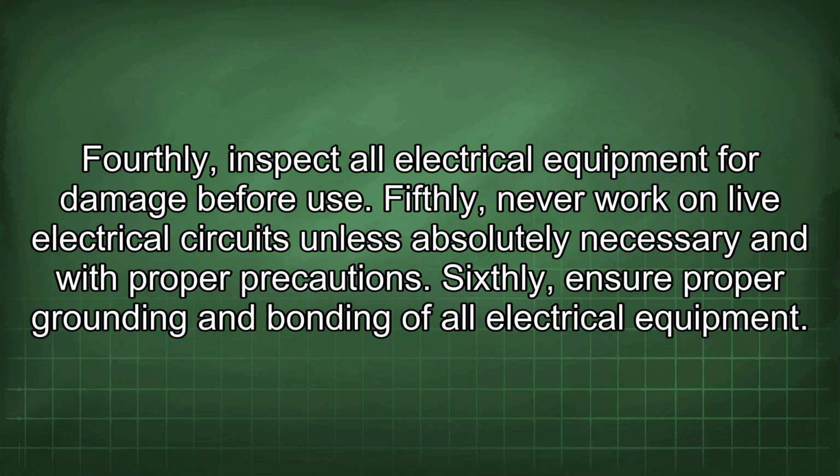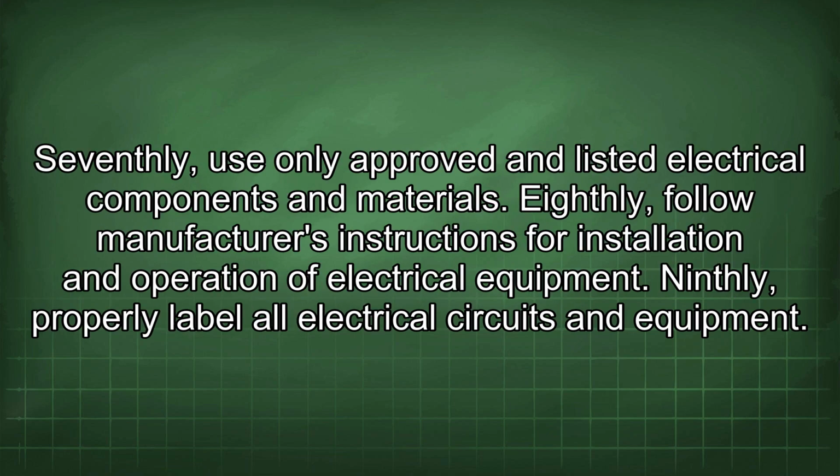Fifthly, never work on live electrical circuits unless absolutely necessary and with proper precautions. Sixthly, ensure proper grounding and bonding of all electrical equipment. Seventhly, use only approved and listed electrical components and materials.